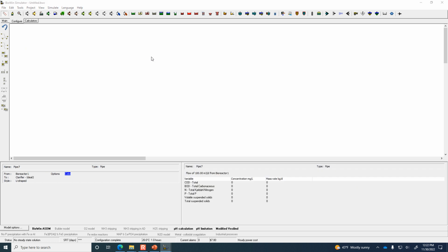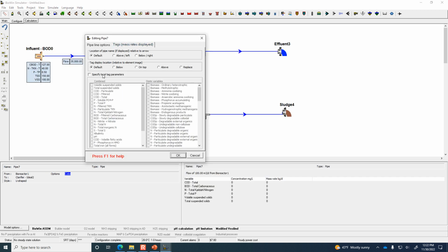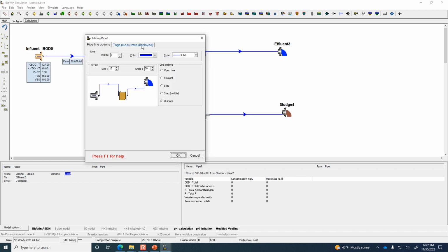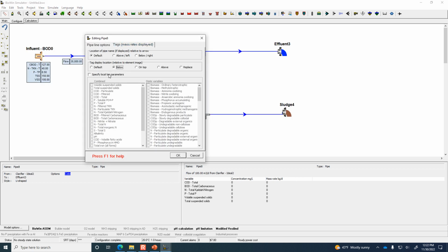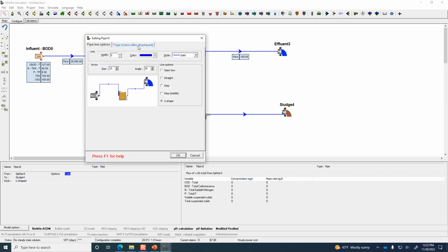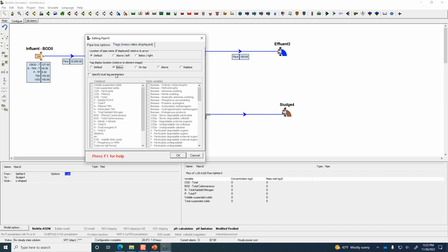Okay, so let's click on all of the pipes, and this is effectively annotation that we're adding with the flow. Now, it doesn't know yet all of the flows, and so it's going to have just kind of a default value, 100 or 1 or whatever. But we'll have it do the calculations, and it'll figure out what's the actual flow once we get to that part.